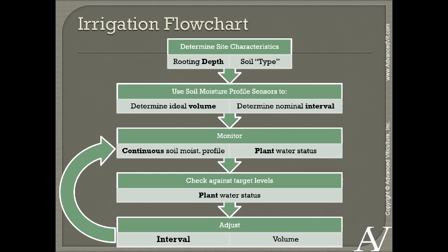It's important to know that, not for the purpose of knowing how deep to irrigate. And it's going to vary depending on where you are. If you're in an arid climate, you may want to irrigate a little past the root zone to push the root system deeper. In a wet climate like here in the North Coast, we really don't need to do that. And actually really shouldn't do that because our root system grows as deep as it's going to go because we almost every year, including this year, start off with a full soil moisture profile.